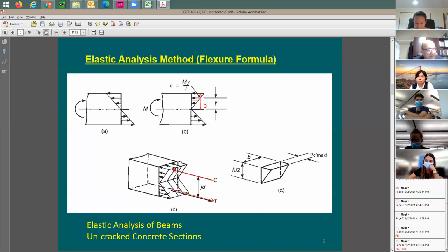So if you take this block and just move it out here, just to study it more in detail, I'm going to say here that this is going to be h/2, the height of this block, and the width is going to be equal to b, and the stress is going to be equal to this sigma c, which in our case, I guess I said that we prefer to use the term F once we start working here with concrete, right? So it's going to be F, and usually we use lowercase. If you use uppercase, it means a force. If you use lowercase, it's going to be stress. Okay, this gives you like the column.